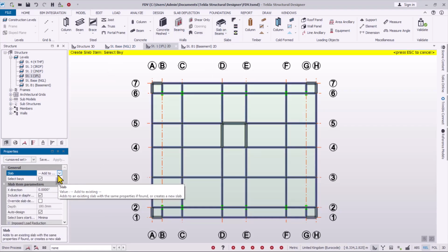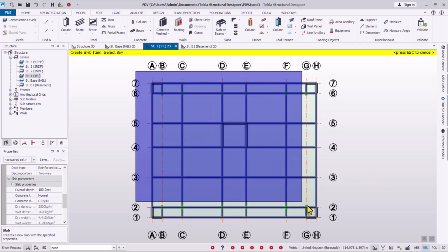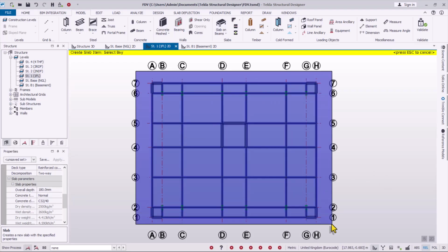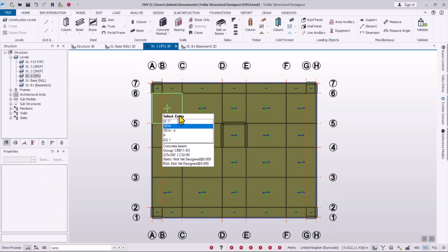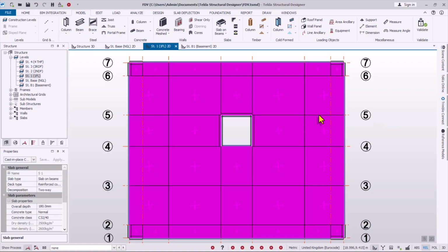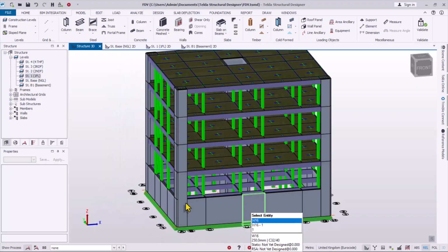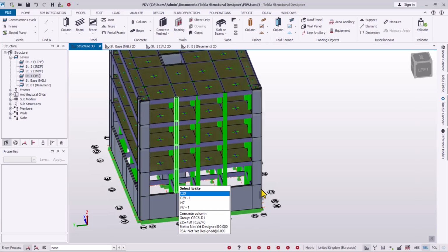All right, so we want to create an existing slab, next one. So if you scroll down right here, you notice we have the depth keyed in before, so everything is good. Over here, it's a two-way slab, so you can actually do a window over the beams, release your hand to have a slab placed successfully, just like this. We'll remove this one right here, escape to get rid of the command, and remove this one. That is for the lift well. Delete that successfully. Go to the 3D, you see. So we have populated this with the reinforced concrete slab successfully, as you can see in the model.